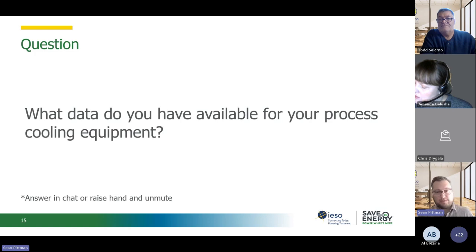Right? If you're identifying something that is a key component in your energy savings estimates, or it's influencing how much energy is being consumed by your process cooling equipment, then you're going to need it in post as well, because you're going to need to follow a similar process to determine how much the post retrofit equipment is consuming. So it is both, and in most cases you're going to need to have that data on both sides of it anyway.